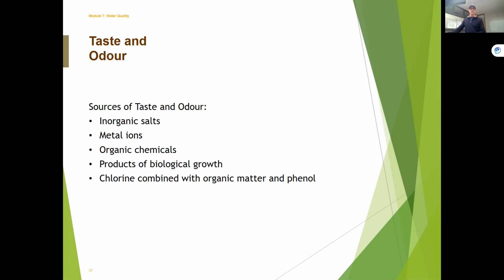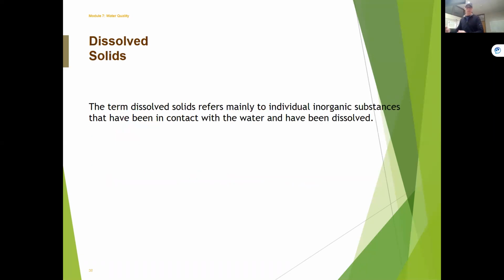Thank you. Okay, so let's walk into dissolved solids now. That's another big one that we talk about quite a bit. And again, that's a tough one. TDS, right? Or dissolved solids. This is all these inorganics that are in the water. Really think about the minerals, all the minerals broken down. It's not just the calcium, magnesium, but this is all the ions with metals and whatnot, and they lump it all together into dissolved solids.